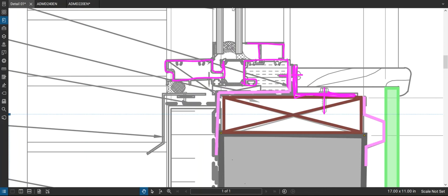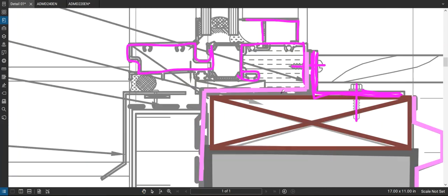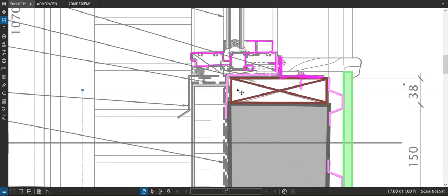If you really wanted to step it up a notch, you could slope this right here, and you'd have to use a leveling shim for the window, but you could slope the top of the blocking there and then put some leveling shims in there. That would obviously use gravity to your advantage, and then run the membrane up on the slope. But nonetheless, what they've got there is okay.